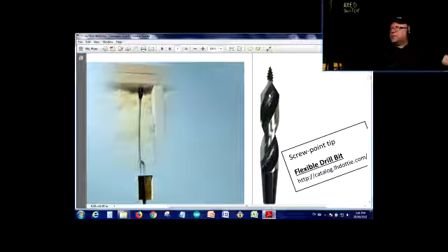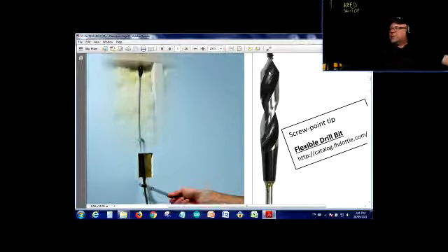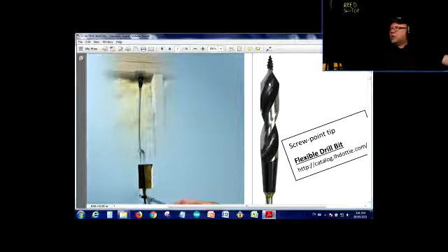Right? So once you hit the middle of the stud, or you think you have done it, you can just make sure that yeah, it is. Plus, when you're drilling, this thing screws into the wood and pulls the drill bit towards the front. Now also you have the flexible drill bit guide. If you cut out an opening here, you can insert that guide and direct the drill bit, and you can feel if you hit the wall this way or that way, then go somewhere halfway in between. That's going to be half of the stud, and then start drilling.